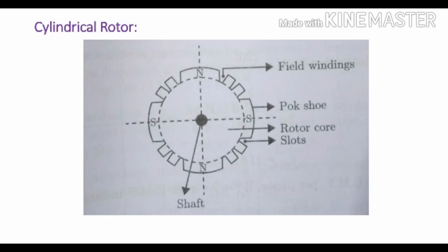It is to be remembered that alternators using salient pole rotors produce a lot of noise, whereas the alternators using cylindrical rotors do not produce much noise. In both the types of rotors, field windings are supplied with slip ring and carbon brush arrangement.